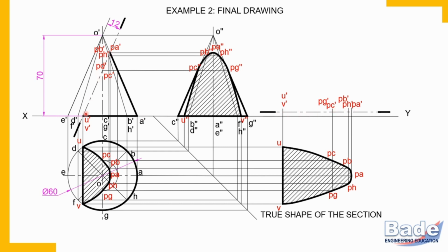So remember this, it will help you to solve some other problem. That is, true length of base of the parabola appears in the true shape of base as line UV, and true length of axis of parabola appears in front view, and that is parallel to boundary generator. In this problem, just now we have discussed about base and the axis is not significant, but in some other problem, it will help you. Let's solve next problem.